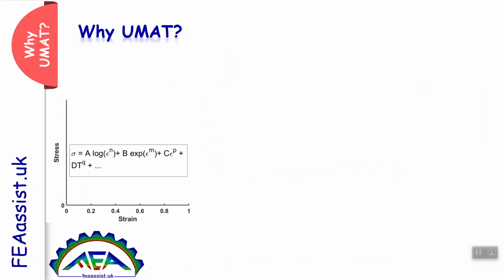So what you can do, then you need a place to write this equation or your equations and define for Abaqus that the material obeys this behavior to solve my problem. This is the reason we need UMAT, because our equation is new.